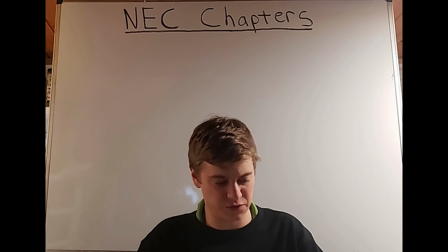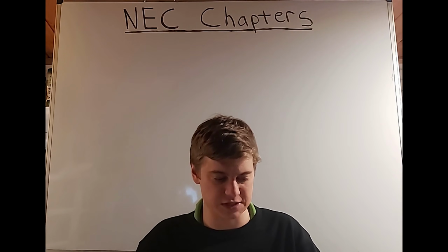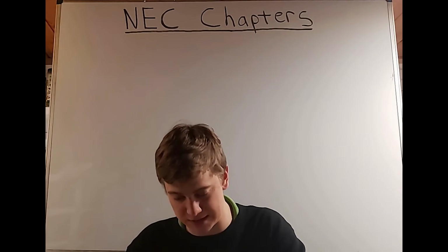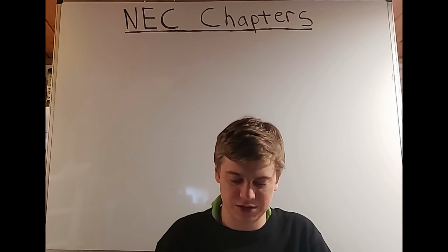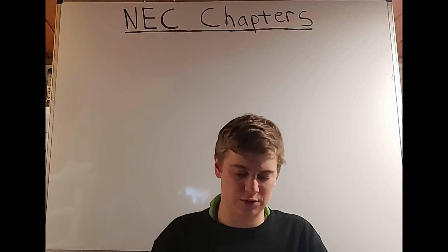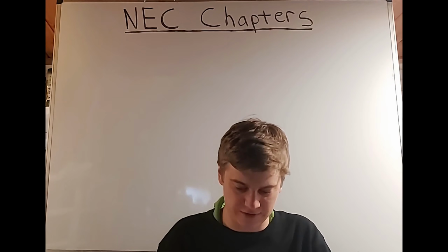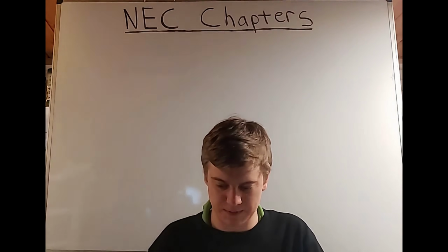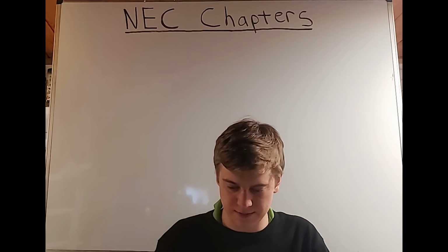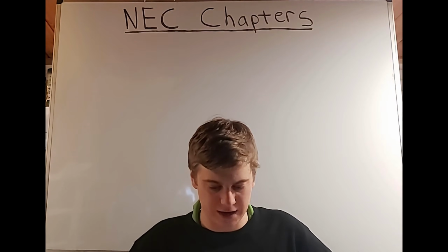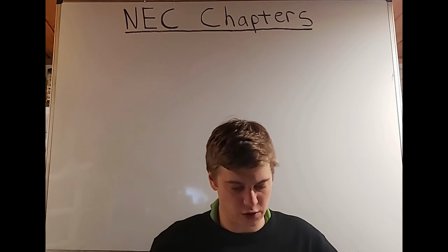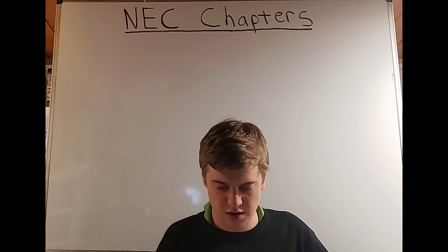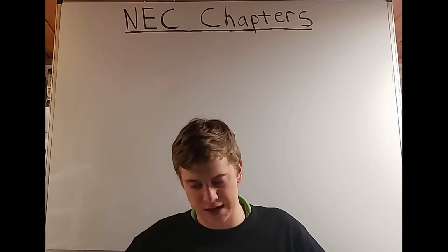You're basically going to use 430.248, the FLC for single-phase AC, and then here 430.250, the FLC for three-phase alternating current motors. Here you'll see it mentions it has induction type squirrel cage and wound rotor amps. Okay, so you have the squirrel cage there, you have the wound rotor, and those are induction type. Next you see you have synchronous type, unity power factor amperes. Okay, you have some more tables and we get into article 440, air conditioning and refrigeration equipment. Then we have article 450, transformers and transformer vaults, including secondary ties. Article 490, equipment over 1,000 volts nominal.